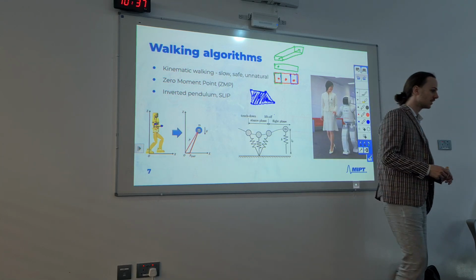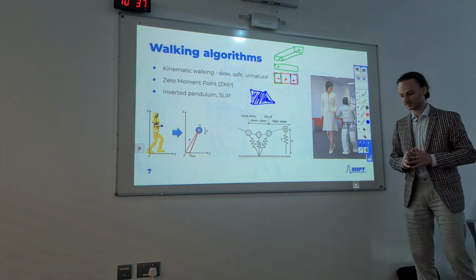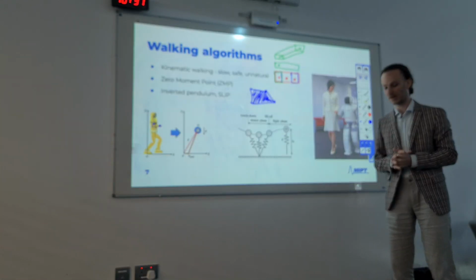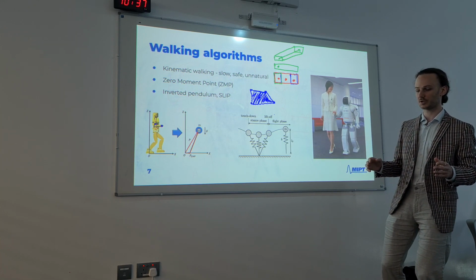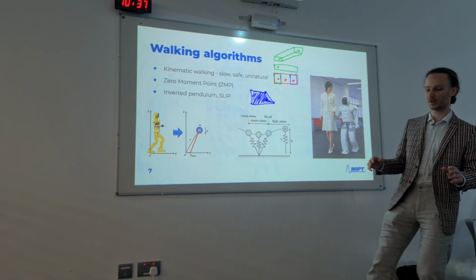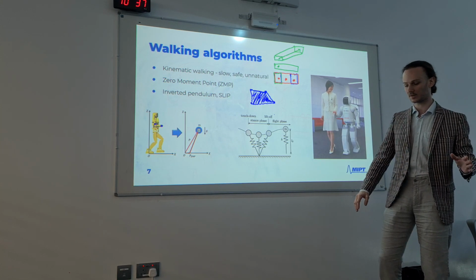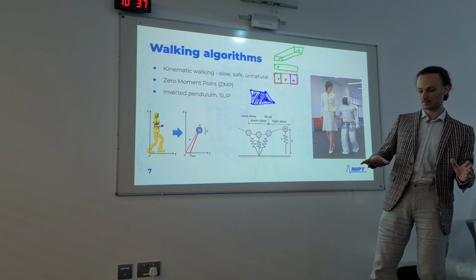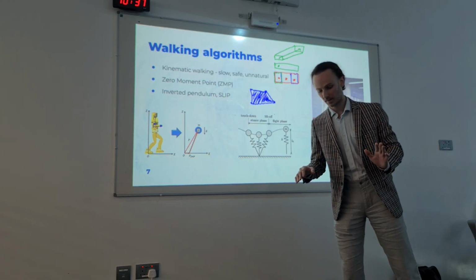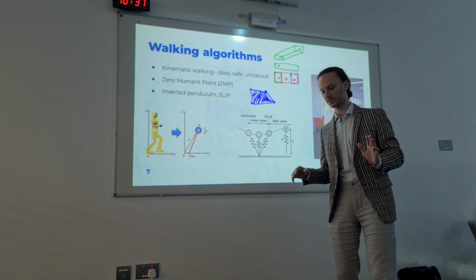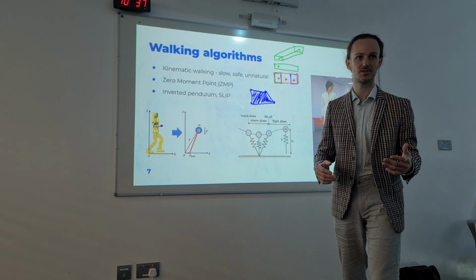And actually, it will give you the safe and slow and not very effective gait. If you're not allowed to use your dynamics, you have to move very slowly. So all these phases are there. We move the center of mass to the new desired support polygon, and then we repeat this whole process. At no point in time do I have any considerable velocity.